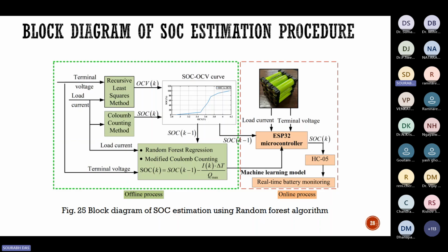This model and the SOC OCV curve we put in the ESP32 microcontroller, and there, while we are measuring the load current and terminal voltage, using this model we can get the SOC, and we can monitor it using the HC05 Bluetooth module, so we can monitor the real-time data on the system host computer.